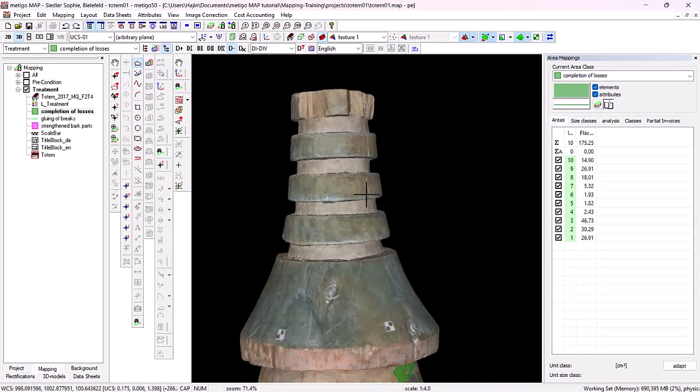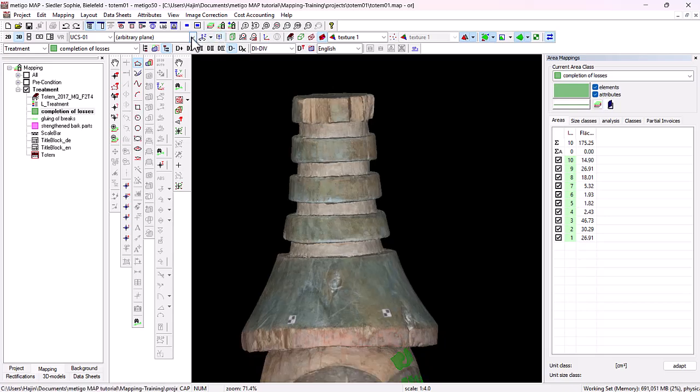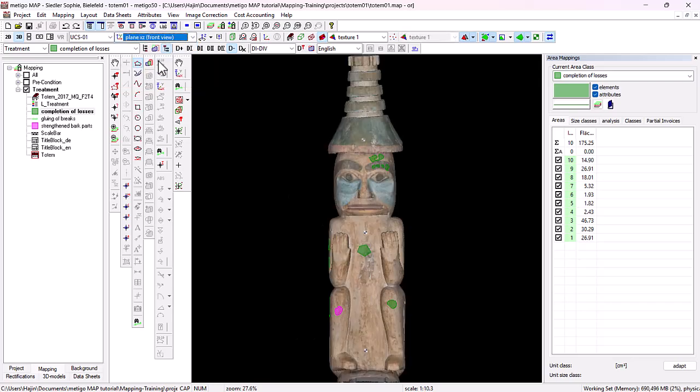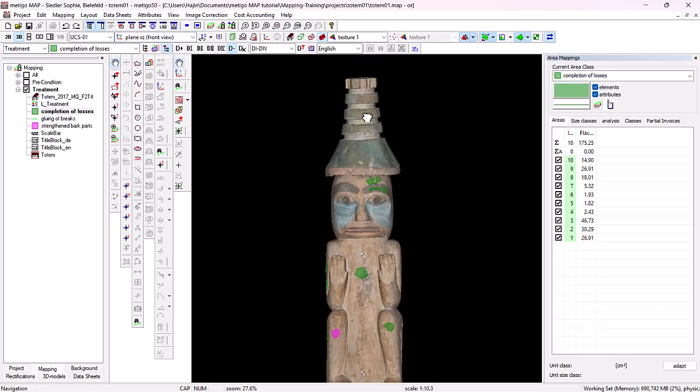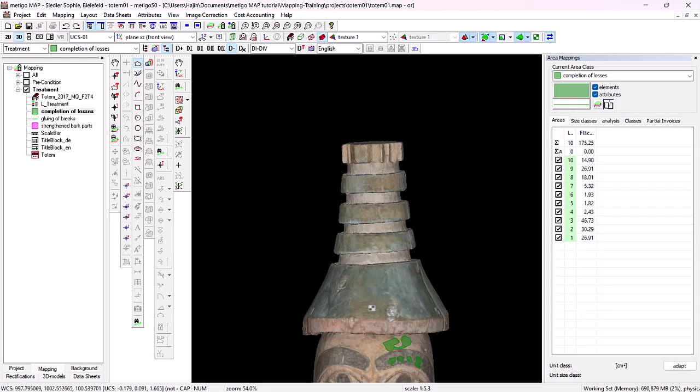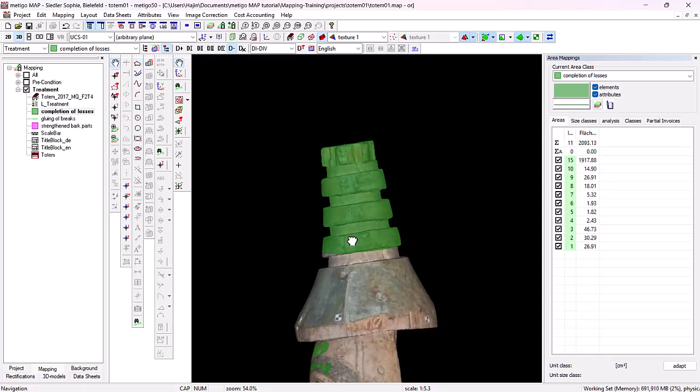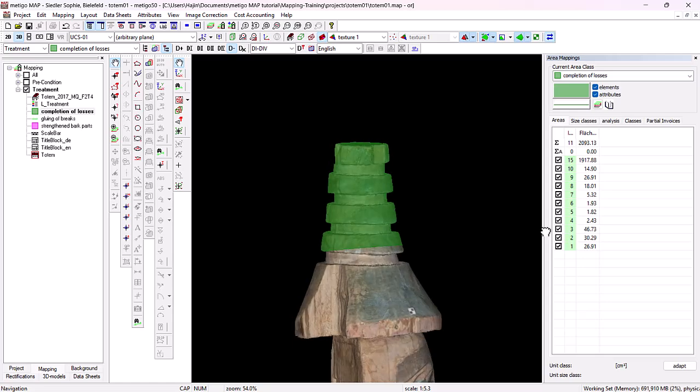and now switch to ortho projection. And I go back to the view on UCS 01 and now apply the same command again, but in the orthogonal view. I close with right mouse button, and then I can see now that I don't have a perspective in it, but I'm orthogonal to the view.